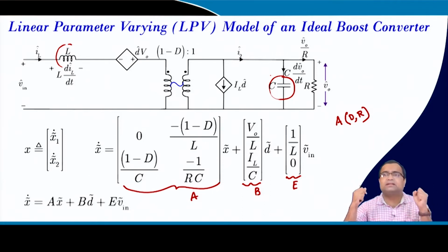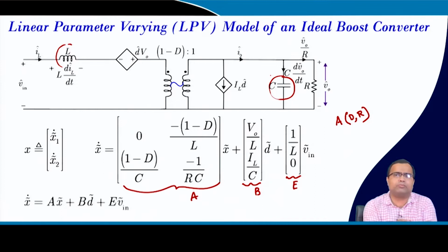So, the inductance may not behave like a constant value if we operate towards the saturation or the nonlinear region of the magnetic curve. But if we operate in the linear region, then the inductor will be more or less constant and the variation is not very significant. The same is true for the capacitor. So, we are assuming the L and C variations are insignificant and those are fixed at the design stage.